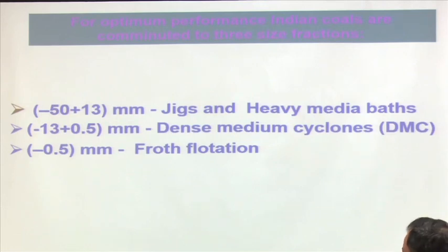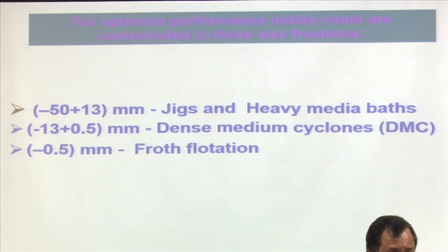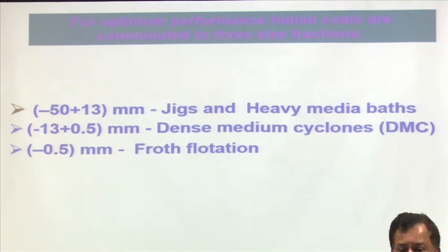Suppose a 40 mm coal has two density classes, like 1.5 and 1.7. If I put it into water, the settling velocity difference will be huge. We can calculate that, because the size also controls the mass of the particle. But when the size goes into the finer range, my mass is getting lesser. So, I face more difficulty in separating them in a fluid medium because their settling velocity difference is less.